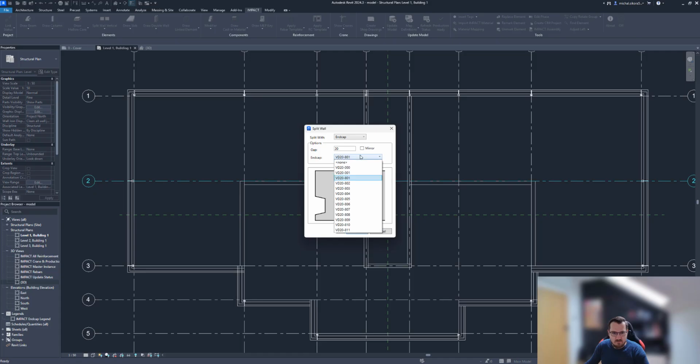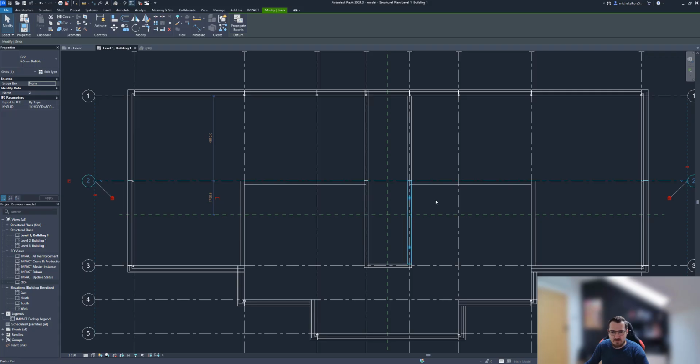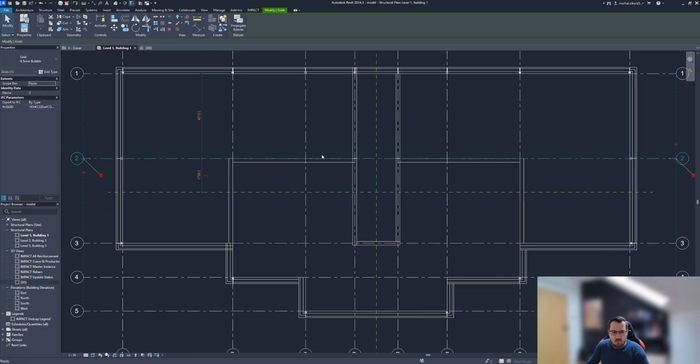Oh well, I don't need to apply an end cap, a specific end cap between those two. We'll do a connection anyway. This will be a 3-point connection between those walls anyway. And again, 3D view, we've got everything in. It's there. No more warnings about the end caps.